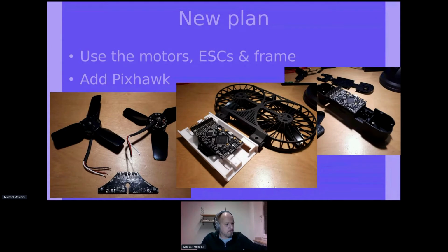So the idea was, instead of building the whole mechanism myself, to just use that cage, which is pretty sturdy, has the motors installed, has propellers installed. They are also sturdy and of good quality, and the ESC was already fit inside. So all I had to do was add some power and a pulse width modulated signal, and I would have been good to go.